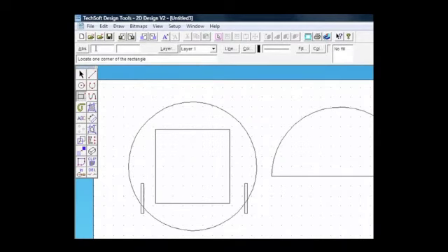Okay, we need to put some slots in here now. The first slot is just a rectangle. Absolute coordinates 230 by 245. And the rel is 3 by -40. Okay. There we have one of our slots.